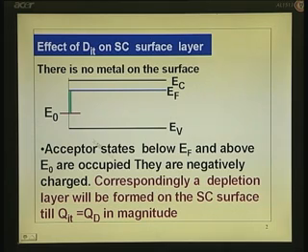Correspondingly, once there is negative charge in the surface, it has come from somewhere. It has come from the bulk of the semiconductor, very close to that point, just below the surface. If those electrons have come from there, it leaves behind positive charges. What you mean by that is, just below the surface there is a positively charged layer, in the sense there is a depletion layer.